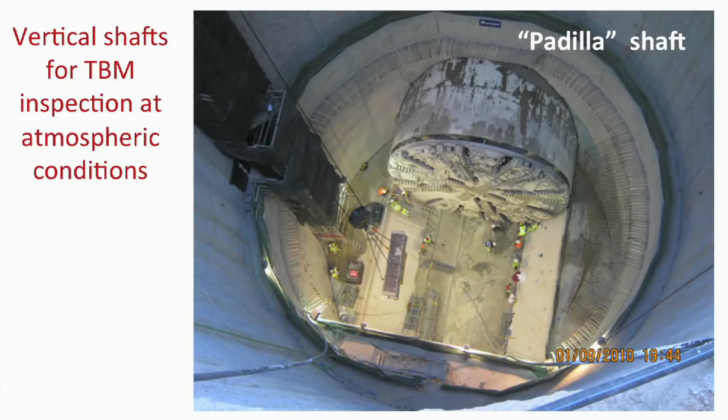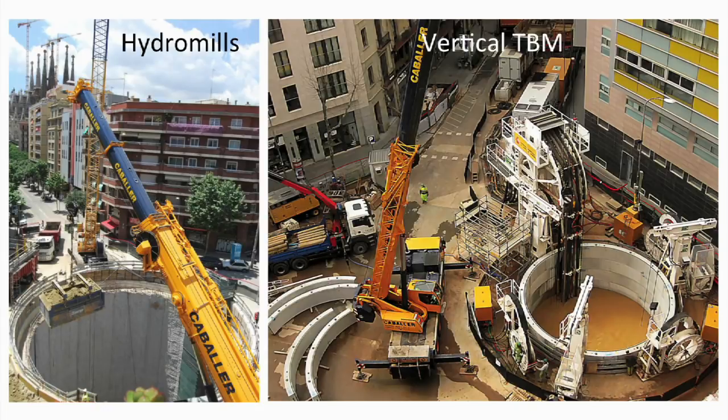Of course we took a number of precautions. You have to take care of the machine before entering a critical part, and this was done by a number of shafts. Here you have some. This is one, and here is the Sagrada Familia. So it's one of the points in which you stop, and you change all the cutting wheels, etc. at the front. This is a very interesting development, like an earth pressure balance machine, but going in the vertical direction. So this is a way of creating a huge well using a machine similar to the one you use for horizontal excavation.